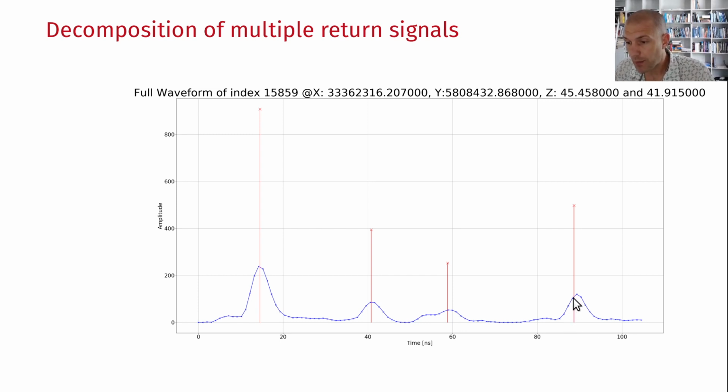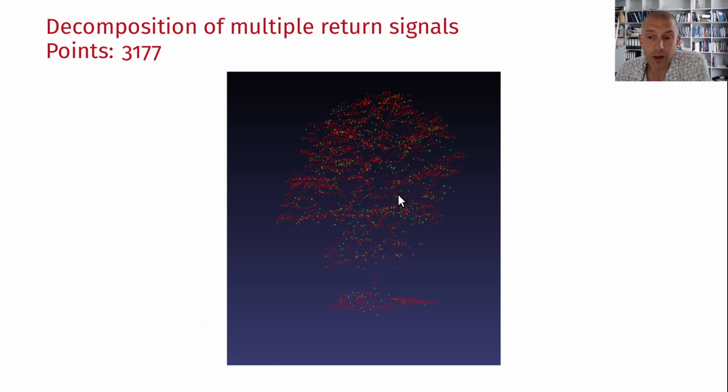The same here, you probably would eyeball the peak of this function at a different position, but if you have two different Gaussians overlapping, you end up placing that point at a different location. So I'm showing this as an example that sometimes in dense vegetation cover, the points may not be exactly placed where you have the feature. It's just a superposition of different Gaussians that may be fitted. But the nice thing is when you look at those full waveform data, you actually can generate your own point cloud, by changing that threshold, by identifying more points that create features.